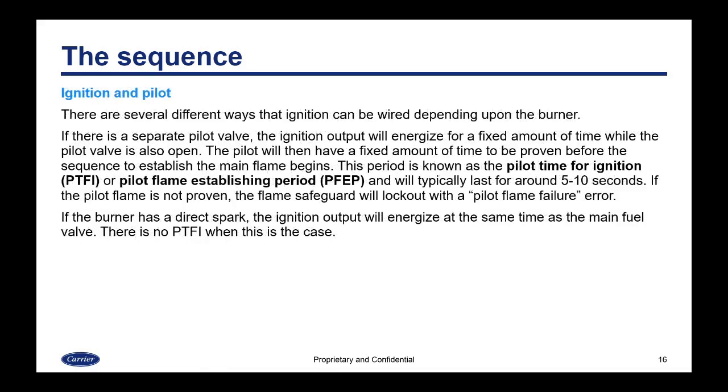There are several different ways that ignition can be wired depending upon the burner. If there is a separate pilot valve, the ignition output will energize for a fixed amount of time while the pilot valve is also open. The pilot will then have a fixed amount of time to be proven before the sequence to establish the main flame begins. This period is either known as the pilot time for ignition, PTFI, or pilot flame establishing period, PFEP,